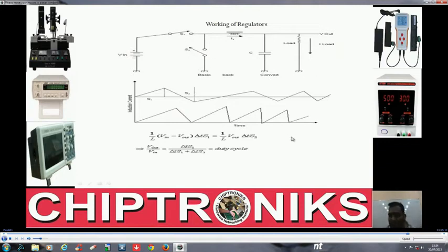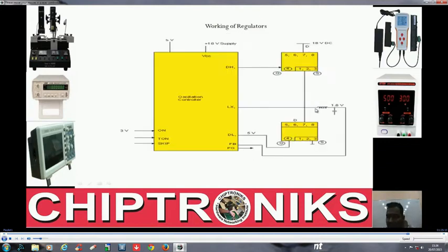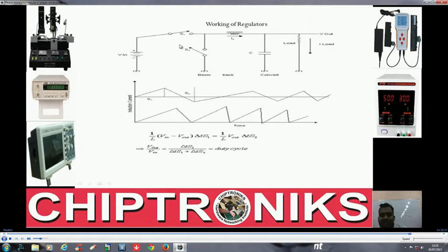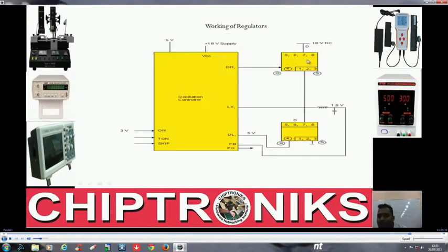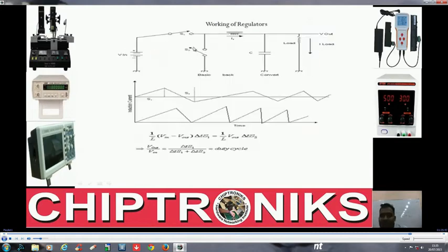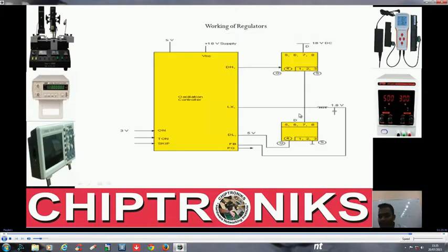So if you check the logic here with a digital multimeter in the case of a CPU regulator, you will get a very low high logic. Low high logic means the upper gate MOSFET will be turned on for a very short time, and the bottom gate MOSFET will be on for much longer, because delta S1 represents the top gate MOSFET and delta S2 represents the bottom gate MOSFET.